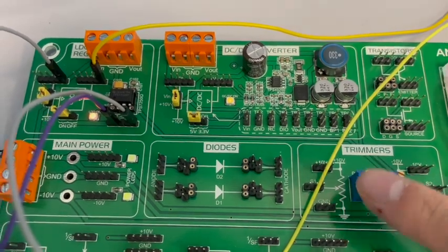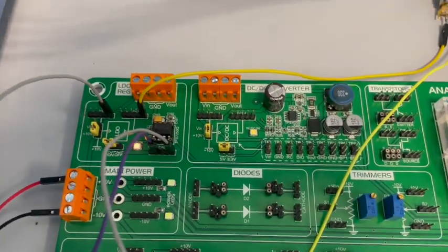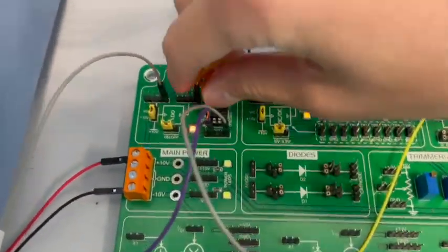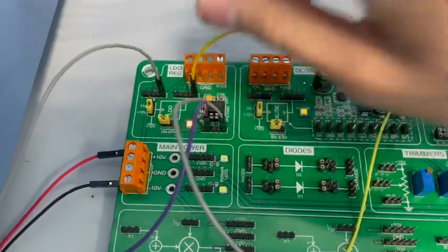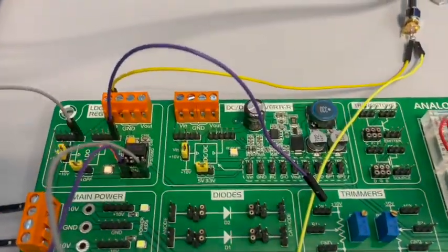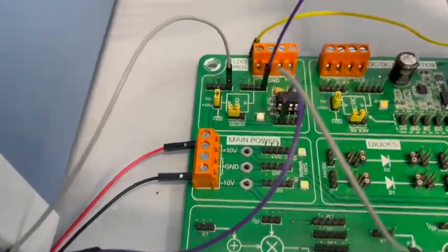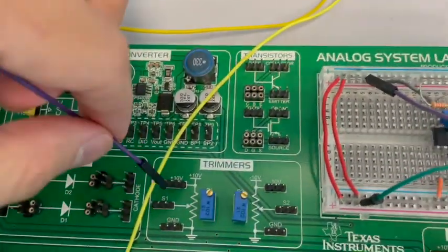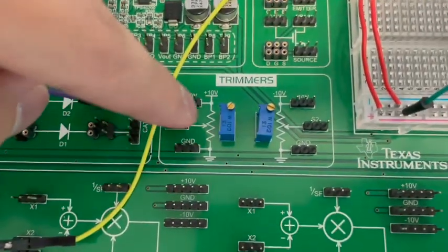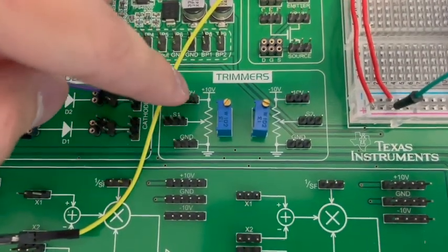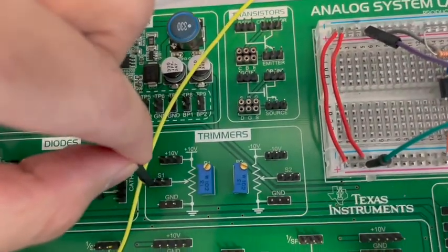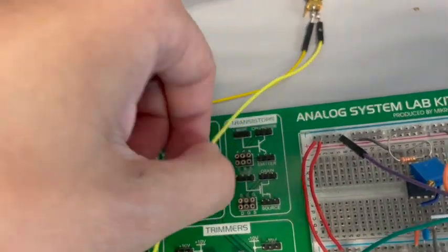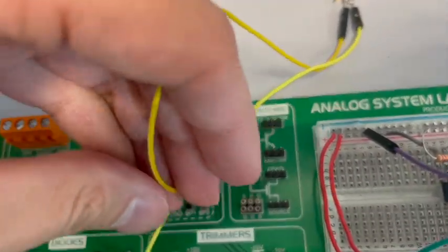with a step of 100 ohm. So you should take a jumper, take this out, and connect this jumper to one of the pins of this trimmer, let's say to the S. You have to measure the resistance between S and plus 10. Connect this plus 10. Connect the output of the signal that goes to the oscilloscope to the other pin.